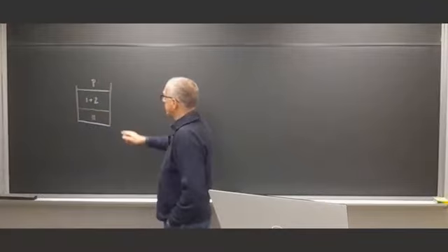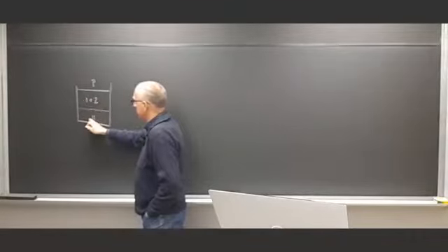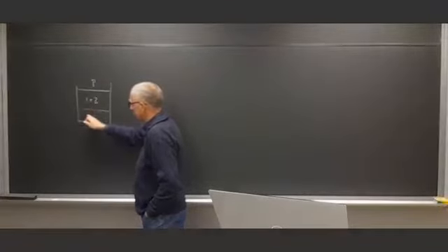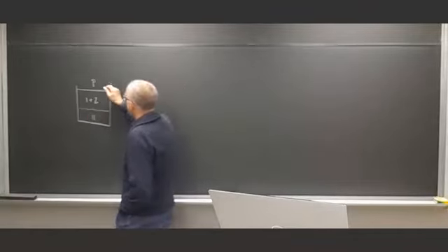Now the setup here is the setup of Raoult's law. We are at pressure P. We have water vapor plus, let's call it, the other products of combustion. And water vapor is the one that can condense, at least part of it, at a given temperature.